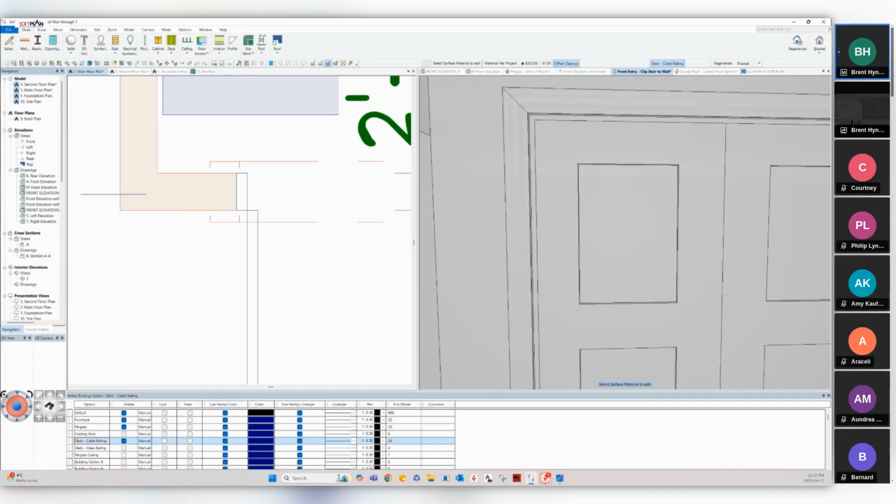In plan, you'll also see that it's barely covering the jamb now, okay? There were a number of changes to openings that were paired with this. We have extension jambs for interior walls that will facilitate different wall thicknesses, because not every wall is going to be a 3.5 inch partition with a 4.5 inch jamb.